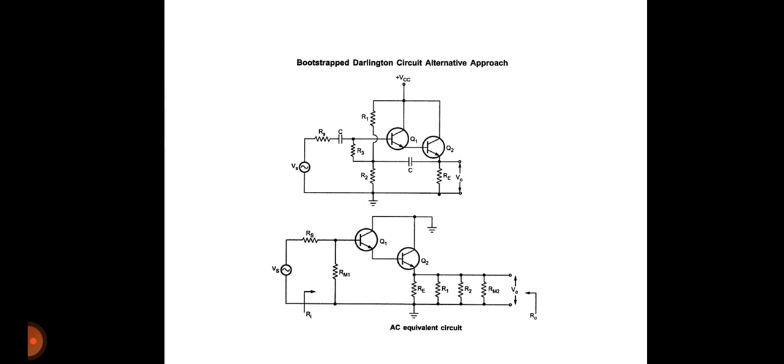So when the capacitor is shorted, this will be connected, actually directly connected to where? So here R1 and R2, and the last one is RM2, and this is RM1. Why RM2, RM1? So this R3 forms the feedback, no? Therefore using Miller's theorem, it should be connected across the input and across the output as RM1 and RM2.